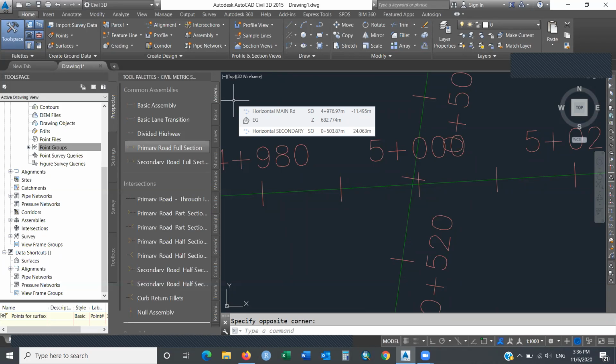So I can, if I want, introduce a piece of a corridor in one of the alignments, but don't run over the intersection, because the intersection will have its own corridor section. I'm gonna repeat myself.